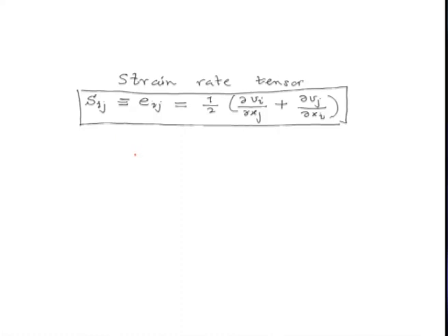That is, we can easily establish that Eij is half of gamma ij dot, i not equal to j, and similarly Eii, or E alpha alpha, becomes del V alpha over del X alpha, no summation over alpha.